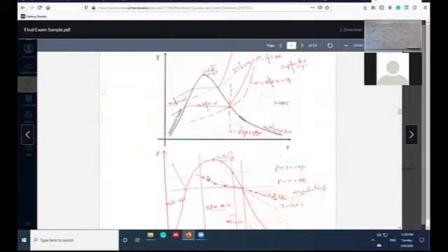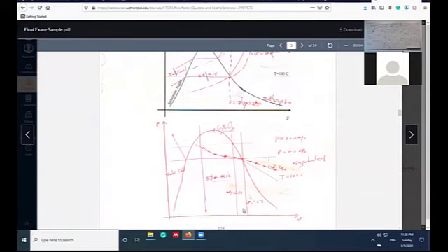Okay? The isentropic line, the constant entropy line in the PV diagram. The constant volume line is vertical, just vertical lines. The pressure lines are horizontal. Temperature lines are like this. This is a constant temperature line.